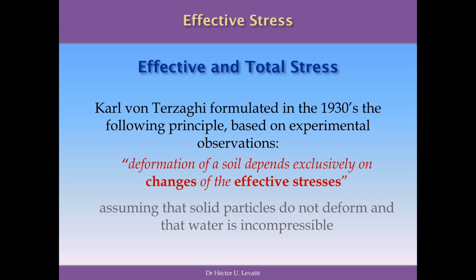And remember, it was discovered by Karl Terzaghi, who is the most important person in geotechnical engineering in the 1930s. And the concept you have to remember, independently of the complexity of the tensors you use to analyze the problem, is that the deformation of soil depends exclusively on the changes in the effective stress.